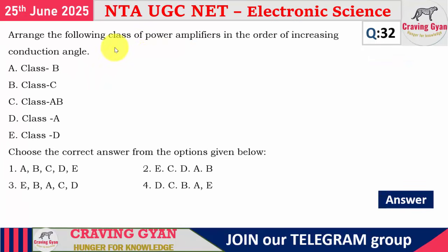32nd question, they are asking to arrange the power amplifiers in increasing order. We know that in the case of class B amplifiers, it is 180 degree. In the case of class A amplifier, it is 360 degree. In the case of class AB, it is 180 to 360 degree. In the case of class C amplifier, it is less than 180 degree. And in the case of class D amplifier, it should be 0.